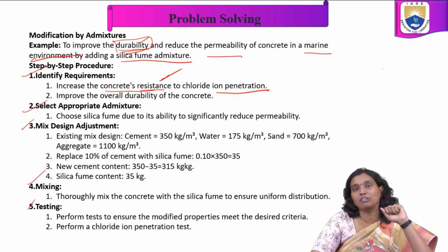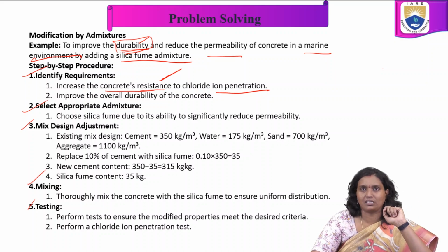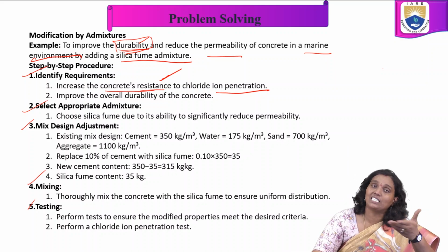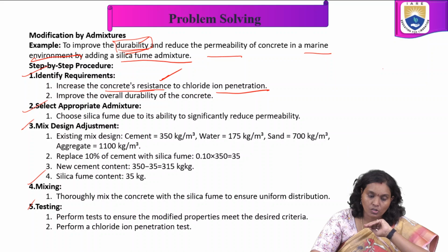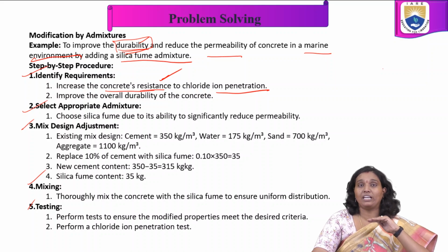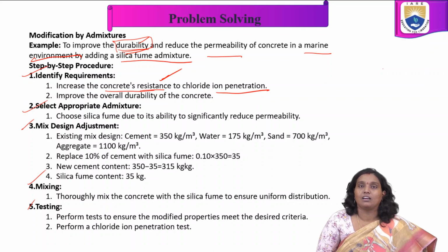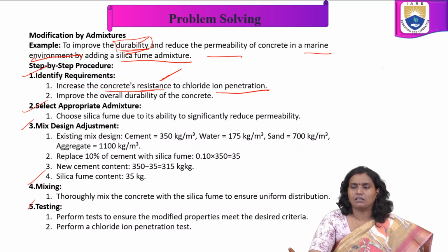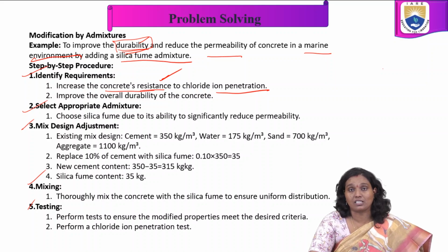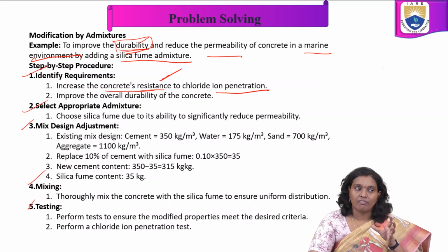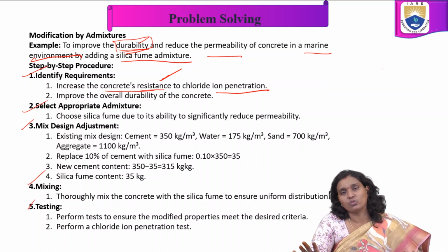In coastal regions, we may observe this. The concrete corrodes and rust will form, because of the higher humidity in those regions. So for getting durability, we have to increase the concrete's resistance to these different kinds of chemical attacks. Sometimes acid rains also affect structures because of the various chemicals involved.